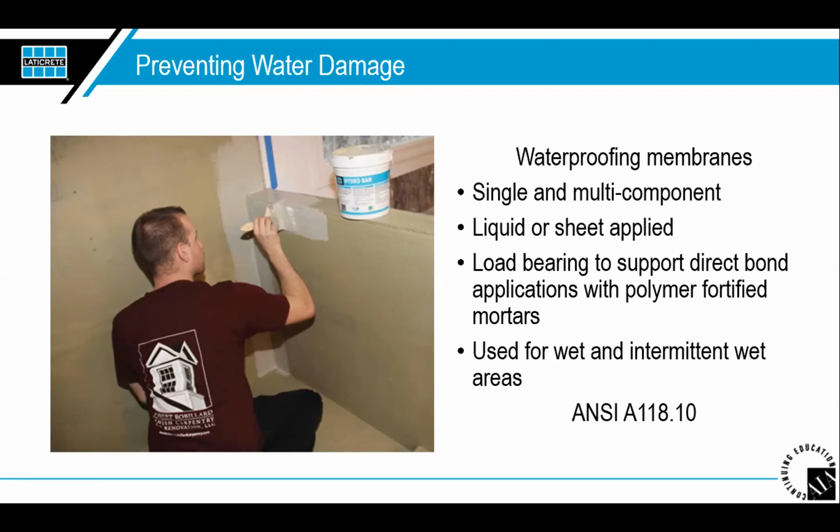Any interior wet area installations like tub surrounds, showers, countertops, and any exterior vertical applications on buildings should be waterproof. The waterproofing membrane helps keep the moisture from getting in the substrate, where it can cause what we were talking about, the wicking and different types of damages like delamination. Properly installed waterproofing prevents water damage, and it can also prevent mold and wood rot. Exterior installations over occupied space, for example decks, require waterproofing systems, which will probably even incorporate a primary roofing membrane. So that's another thing to think about too.